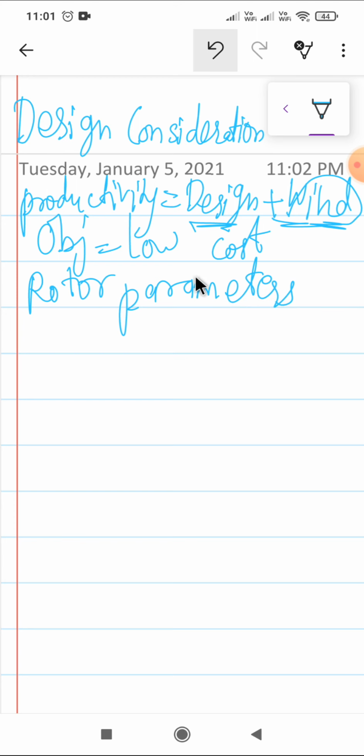So the choice of an aerofoil, then an initial blade shape is found using optimum blade shape assuming wake rotation. The final blade shape and performance are obtained iteratively based on drag, tip losses, and ease of manufacture. So we will find the parameters.